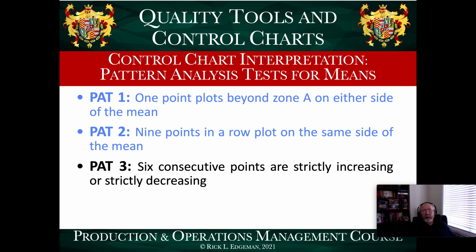So if you're looking at the diameter of drilled holes and you're staying with the same drill bit, it could be that over time the drill bit is shrinking in diameter. You'd have 6 consecutive points, let's say the average diameter of the drilled holes, where we sample 5 holes every day drilled by the same bit, and you might see that going down over time.